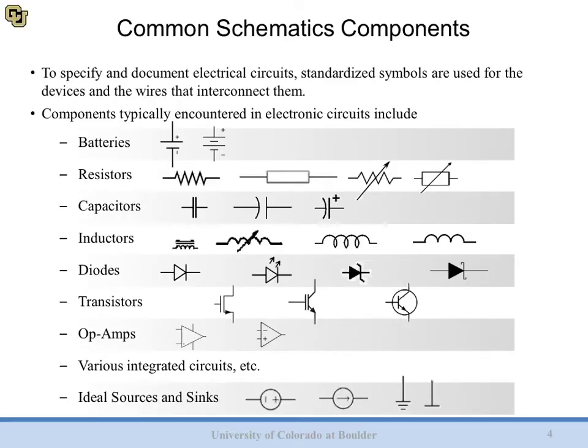When drawing schematics, there's a couple common elements that we use. Many of these you might recognize from previous classes, so we'll just touch on some of the important features. When representing a battery, you can either use one cell or two, and just make sure that matches what you're actually going to have. The two common types of symbols for a resistor are this one you've probably seen before, as well as sometimes just this box seen here. You can use either one, just make sure you're consistent.